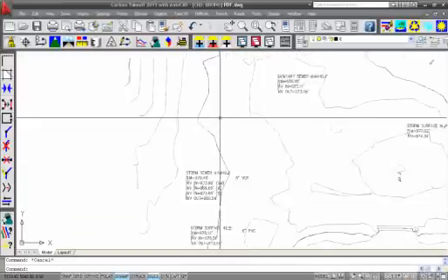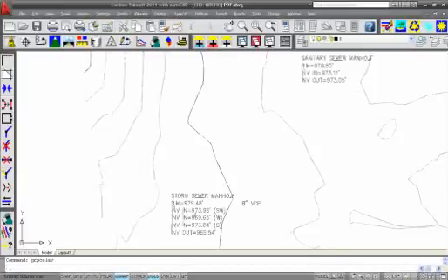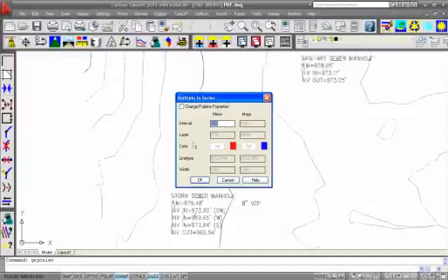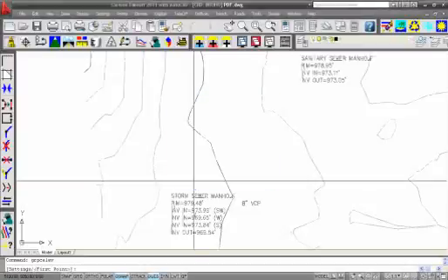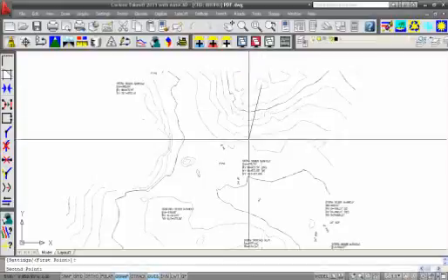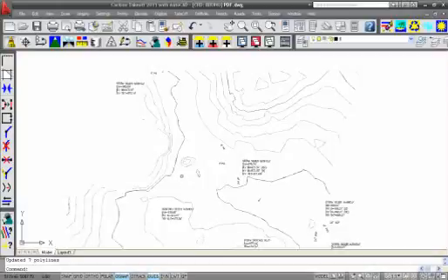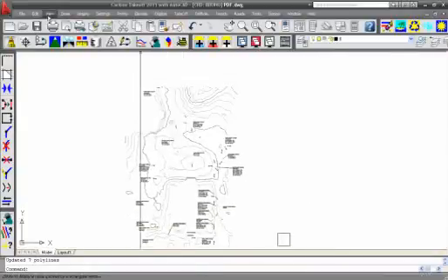And then we have different elevate commands that says elevate, assign contour lines, multiple in series. Say that these were 2-foot contours, and I'm just going to make up some numbers here, going through here to here. Say the first contour was at 100, going up in elevation. Okay, updated 7 polylines, and if I look at my 3D viewer window,